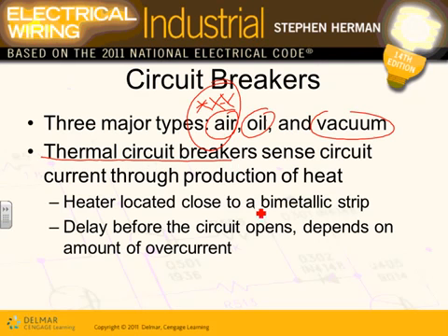There's a heater, and there's a bimetallic strip close to it. It heats them and it will trip the mechanism. They expand at a different rate and it will trip. And you can initiate a delay, of course, on these circuit breakers.